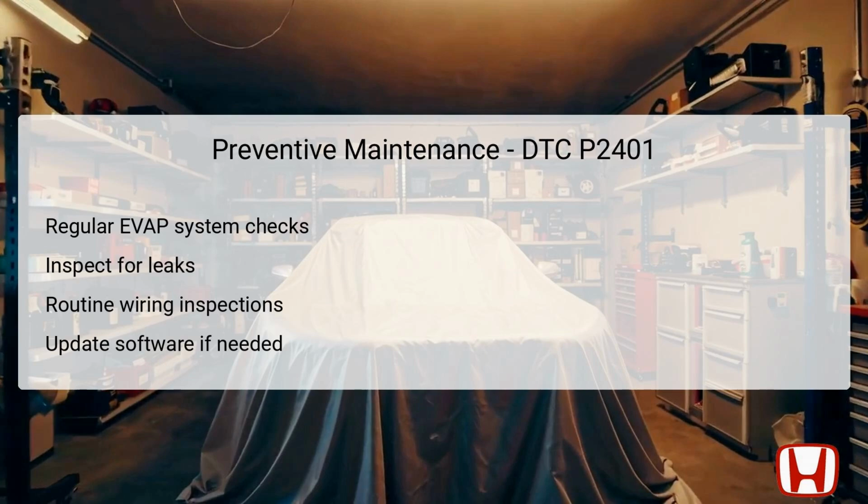Technicians should also consider updating the PCM software periodically to ensure that any bugs or glitches are resolved and that the module operates optimally. By implementing these preventive measures, vehicle owners can maintain a healthy EVAP system and reduce the risk of low voltage issues being triggered again in the future.